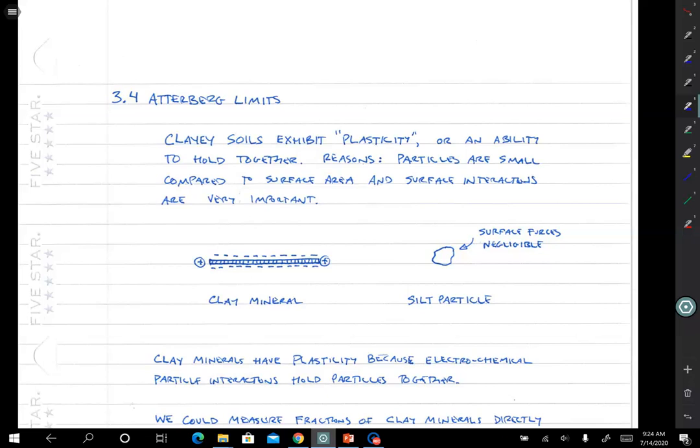I'm sure that you've experienced plasticity before. All of us have played with clay at some point in our lives, and we know that it holds itself together, but you may not have given much thought to what actually is happening there. Why is it that clay minerals hold themselves together, whereas sand particles fall apart? They are, after all, just little particles, right? You can't maybe see the individual particles in a clay mineral, whereas you can see them in sand. And it turns out what's happening is that there are electrochemical interactions between the clay minerals.